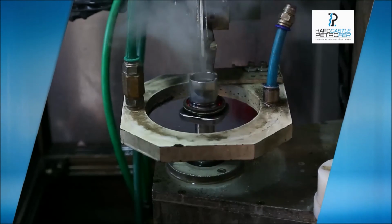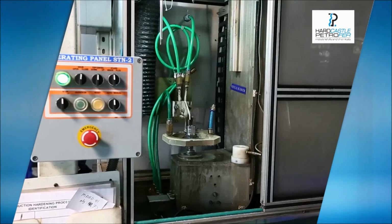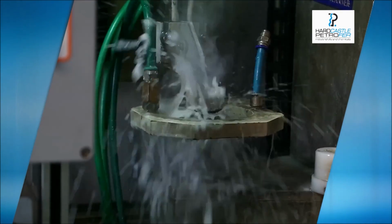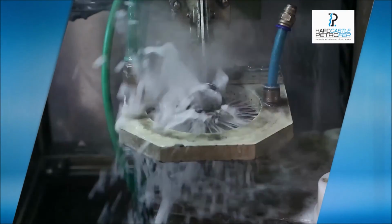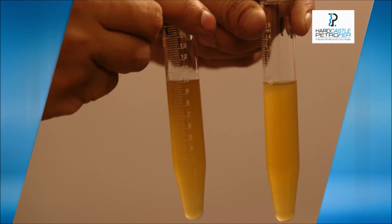The life of water-miscible quenchants is usually limited by several factors. In the case of induction hardening operations, the solution has to be replaced after periodic intervals due to the effects of contaminations from previous processes. The thermal loading can also take its toll in the long term. In view of this, and the need to control the concentration of solution, monitoring is required for polymer quenchant solutions.